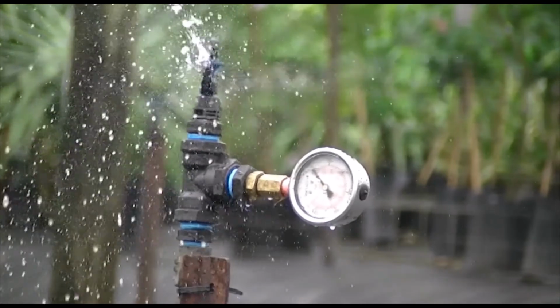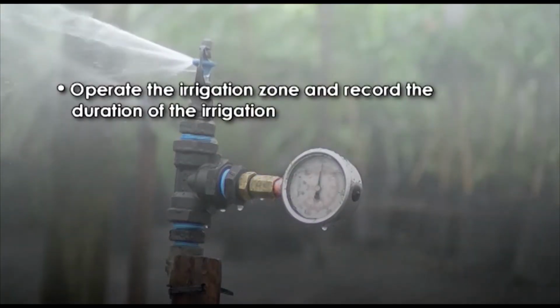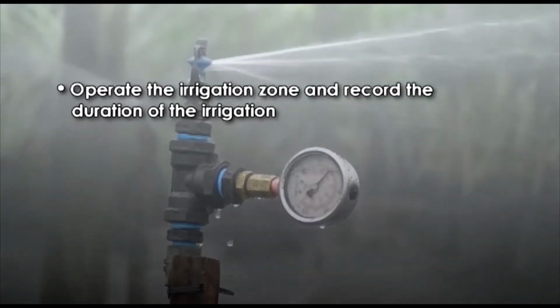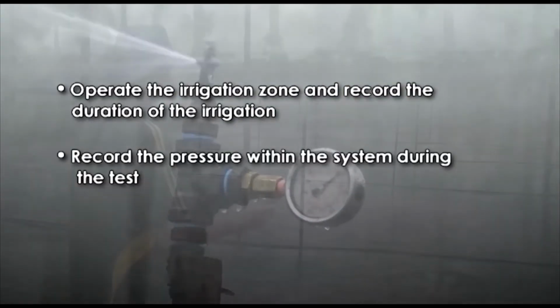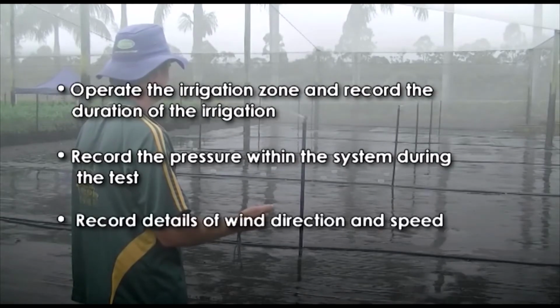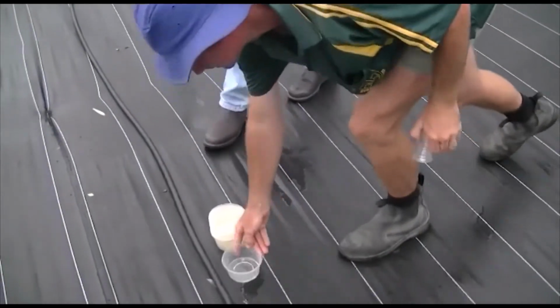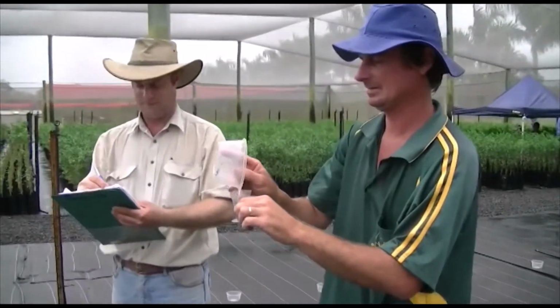Once the area is set up, it is time to run the test. Operate the irrigation zone and record the duration of the irrigation. Record the pressure within the system during the test. Record details of wind direction and speed. At the conclusion of the irrigation test, measure the volume contained in each catch can.